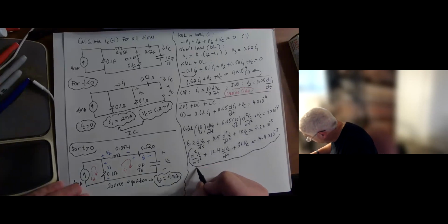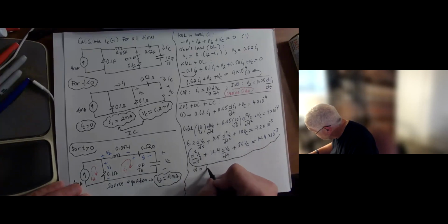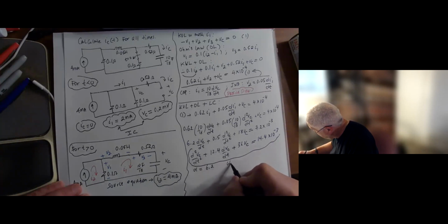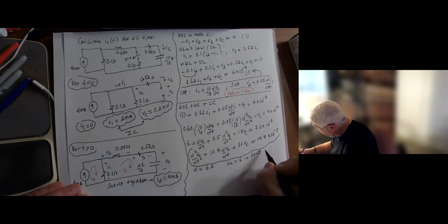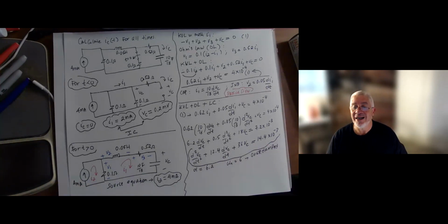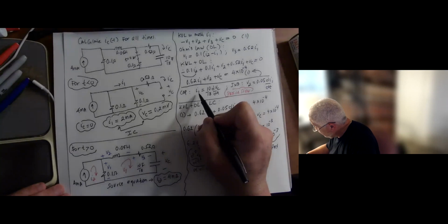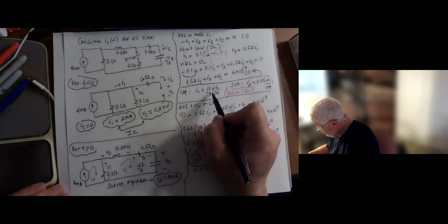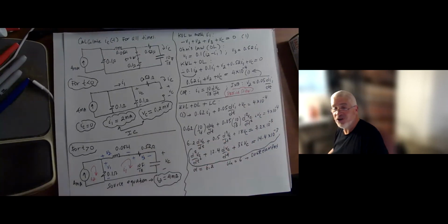Okay, at this point here, what I need you to do for me is identify alpha. Alpha is just this coefficient divided by 2. So alpha is 6.2, and omega n is the square root of this coefficient, which is 6. So alpha is larger, so this is an overdamped case. This is the overdamped case. You're going to need to calculate S1 and S2 and then write the general solution, essentially. So keep in mind here that the capacitor current is also the inductor current, because we're going to need this relationship to enforce the initial condition here.